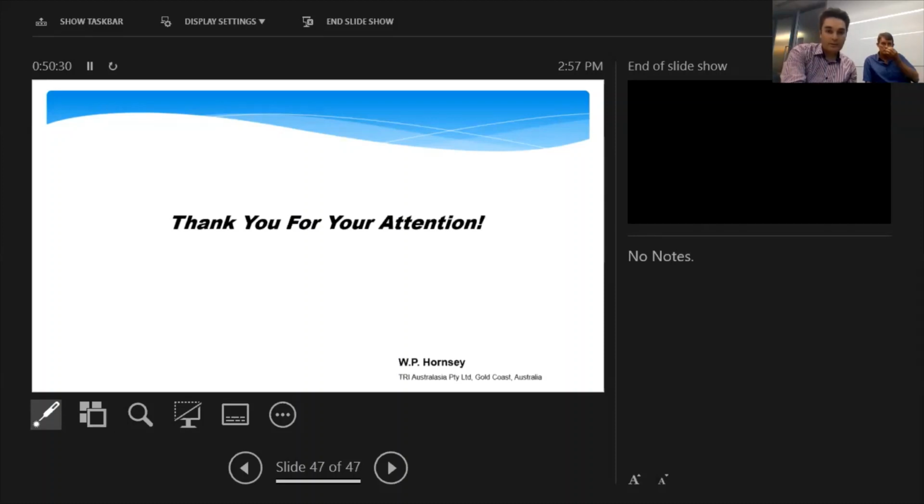So the question, based on the graphs you presented, Warren, which parameter do you suggest for CQA? Is it CBR instead of mass? Is it the right move? Look, I think CBR, if you know what geotextile you've used, I think you have to do the testing to see which one works. And then from a CQA point of view, you can use the CBR to define whether the material is the same material as you've used for your testing initially. So, yes.